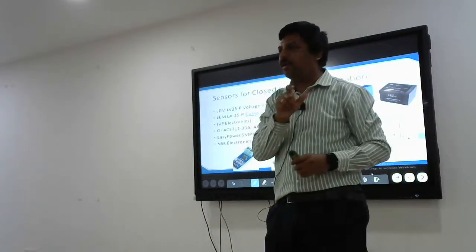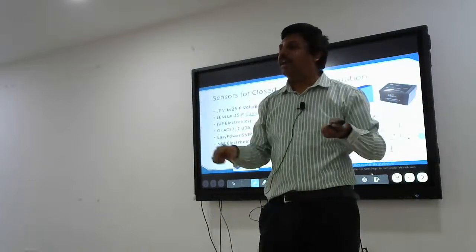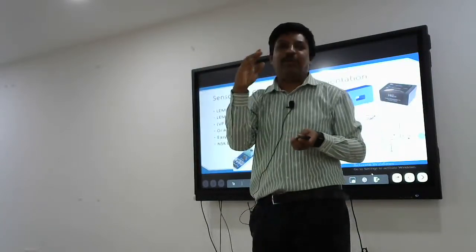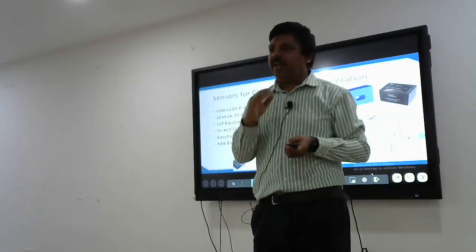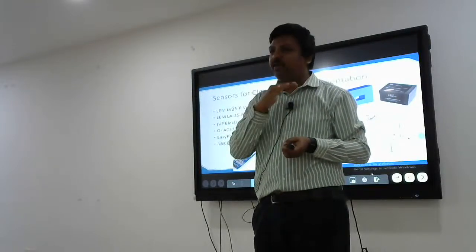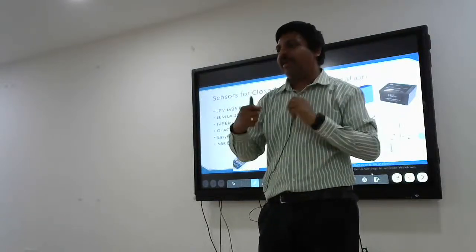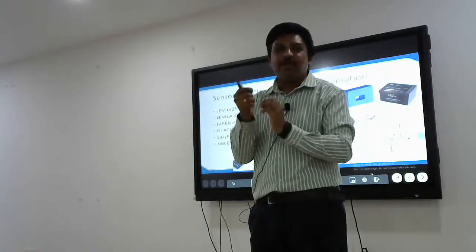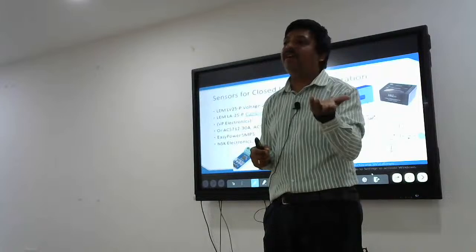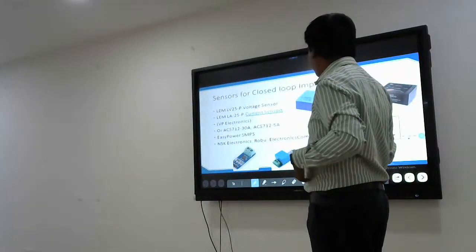But nowadays, hysteresis control has been replaced with VFD control. It maintains continuously at 25 degrees. It controls the speed of the compressor and maintains 25 or 24 continuously. Unlike hysteresis control, there is no on-off compressor. The compressor will be on continuously, but we reduce the speed. That is called inverter compressors. Anyway, I will discuss it later if time permits.